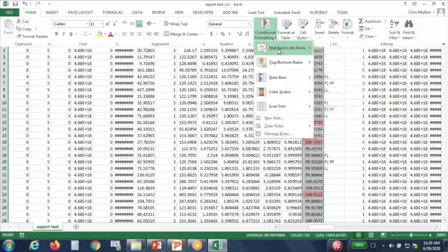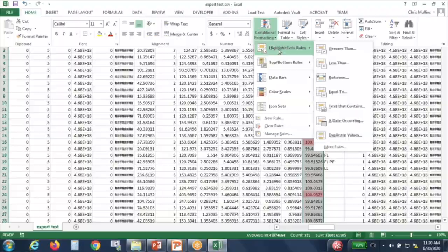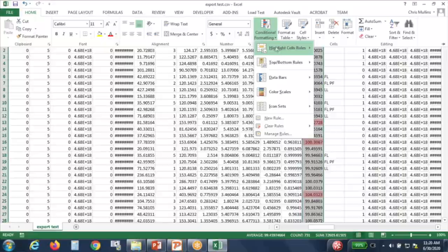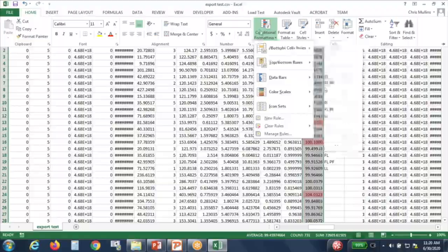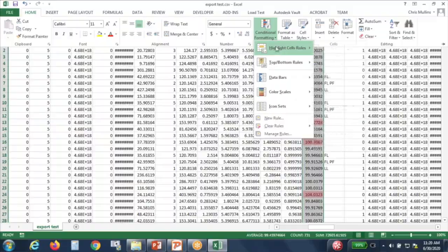So we can do a conditional format on all three of these. I go to Home, Conditional Formatting, Highlight Cell Rules, and Less Than. I want anything to show up that's less than 0.25 amps. Hit OK, and there's quite a bit here. C phase, probably low. If it's got this 0, it's more than likely a service type that's either a single phase service or a network. It looks like a 3-wire network, because you've got current on A and B, but nothing on C. So don't worry about that one.